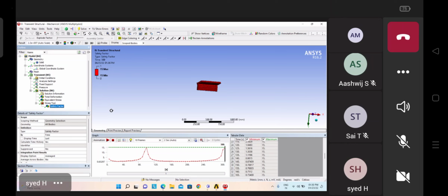Yes, sir. Now we'll start the transient thermal. See here, nothing different you can find here. Only the assigning of boundary conditions is different. Like here we are specifying the force, pressures, bearing load, point load, line pressure. Those things we are specifying in static structural or transient structural. But when you go for thermal, either transient thermal or normal thermal, whatever values we are specifying depend on time. That's it.